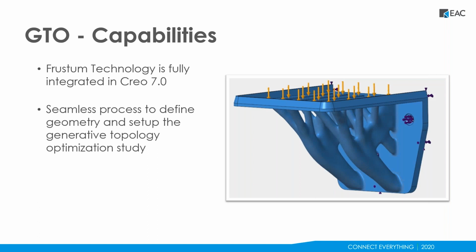So the process, like I said, is integrated. It's very similar to what you might do in Creo Simulate Live or Creo Simulate with respect to defining the loading for your part. You're going to have material, you're obviously going to have geometry, and then from there you would assign loading conditions. You apply a load to a part, and you constrain it or hold it in place.